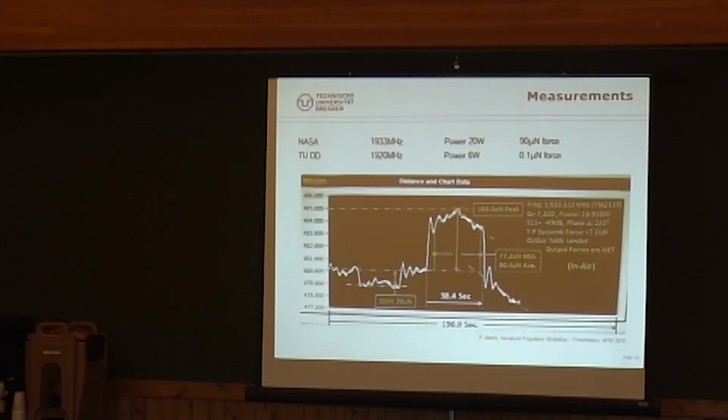To compare this with the results of the NASA measurements Paul March presented at the Advanced Propulsion Workshop in 2016, they showed, at 1934 megahertz and 20 watts of power, a force of up to 90 micronewtons. We can perhaps compare this case with our 1920 megahertz, 6 watt measurement, and we just see 0.1 micronewtons of force, which is noise.